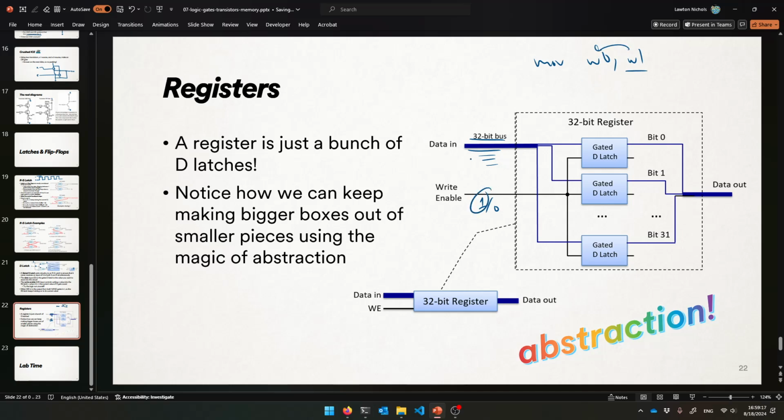So set the write enable high. This information is coming from W1. And then if anybody ever asks for W0 again, they can read from these wires. Does that make sense? Isn't that so cool? We know how to build a register now.